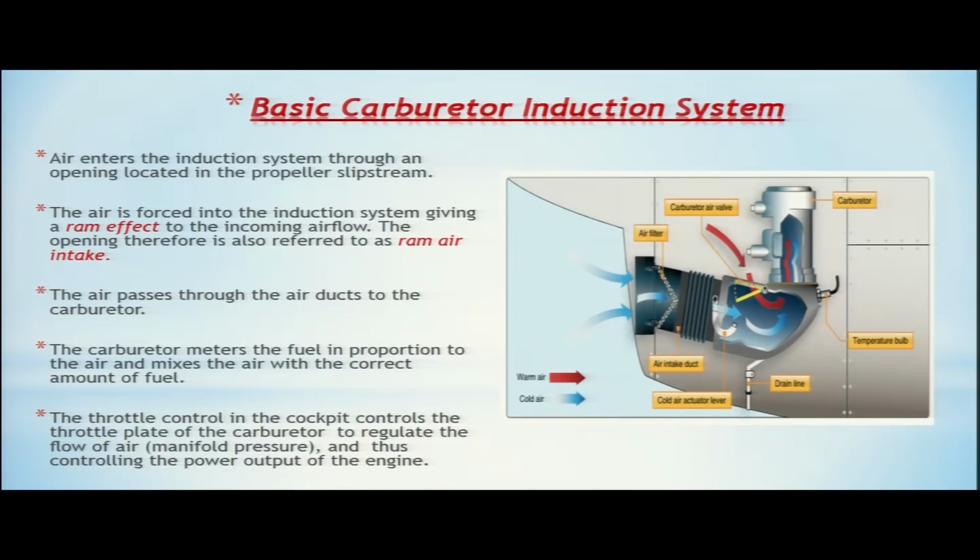Air enters the induction system through an opening located in the propeller slipstream. As we have seen in our first slide also, the air is entering the system through an opening which is located in the propeller slipstream. Here in this diagram also you can see the air, this blue arrow is your cold air coming through an opening in the induction system. The air is forced into the induction system, giving a ram effect to the incoming air flow.